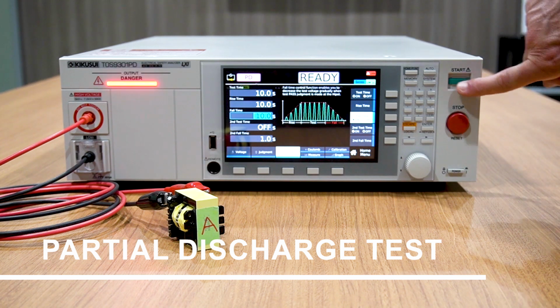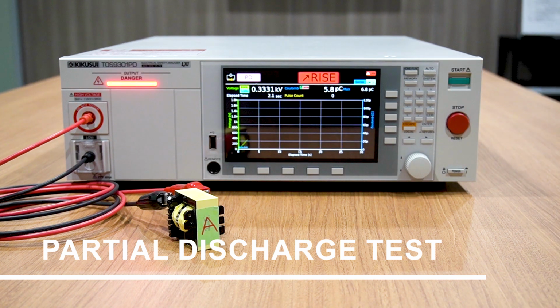Let's test sample A, which is the good transformer, first. The test voltage gradually increases, but no partial discharge occurs, and you can see that there is almost no movement in the amount of charge. This test was completed without any problem.